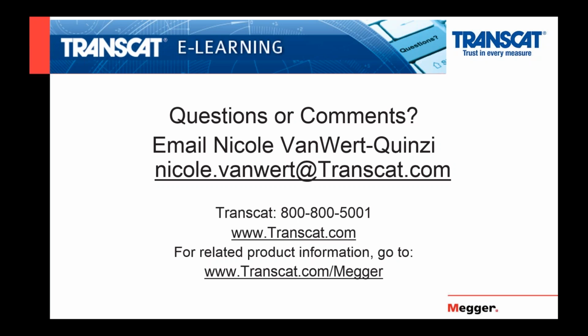Next question. How much current using DLRO should be used for strap measurement? Interesting question. Many times when they use a DLRO, they're typically just using 10 amps to do it. Now, this measurement you're going to be getting is in the microohms, obviously. Regardless of how much current you're going to use, you're still going to have a relative measurement. So what you're looking for is a change of 20%, and that's per IEEE 450. So when I look at that strap measurement, if it's changed by 20%, that's a flag.